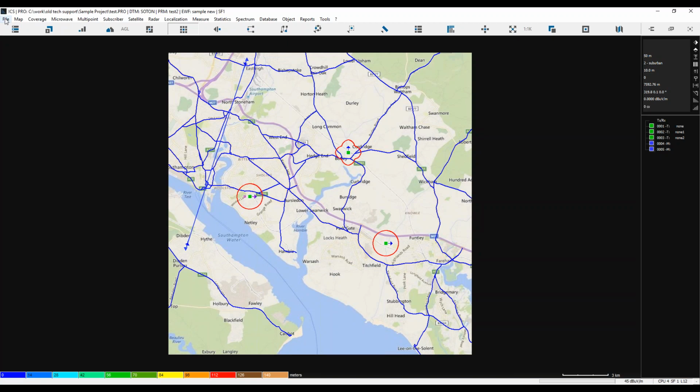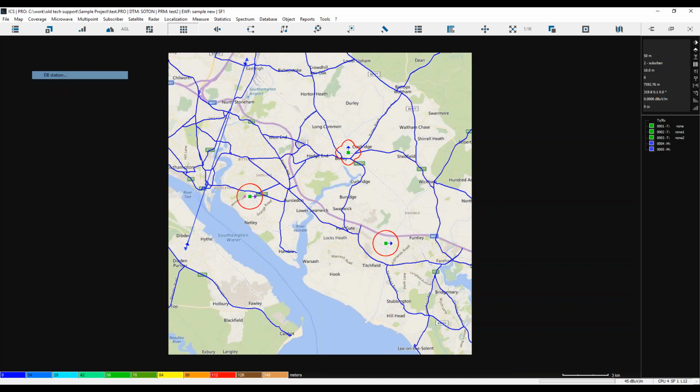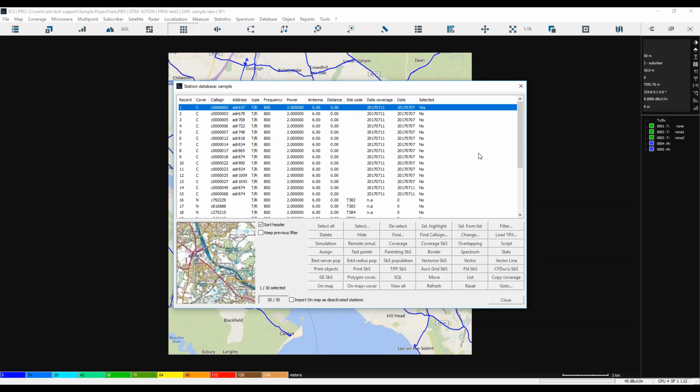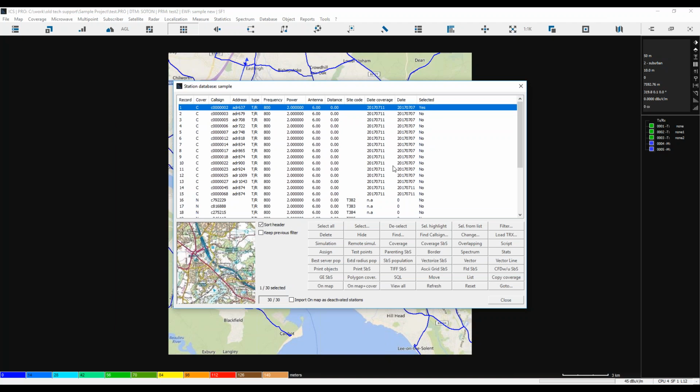Okay, the other bit was being able to export from the station database, this is outputs really, into Google Earth. So this is KML format essentially. I've got a station database here, so I can simply select the number of stations that I'm interested in. I'm just going to select a single station in this case. You can see here it's selected that, and the option that's been added is this GE for Google Earth site by site, and when I hover over it, it gives me a little explanation of it.